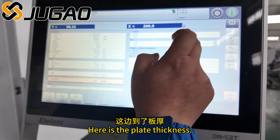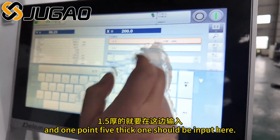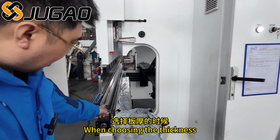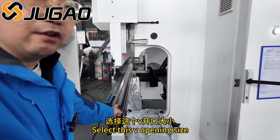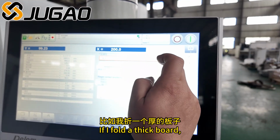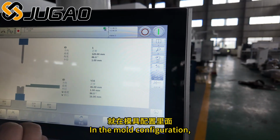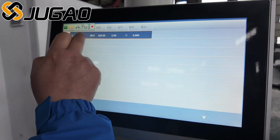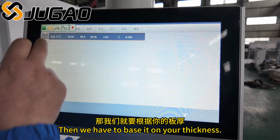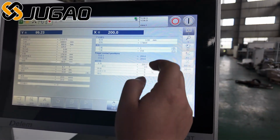Here is the plate thickness. For example, if I want to fold a 1.5 thick one, it should be input here. The plate thickness will be adjusted accordingly. When choosing the thickness, select this V opening size. Generally, it is 8 to 10 times the plate thickness. If I fold a thick board, when choosing the mold later, in the mold configuration, we need to select the upper mold. Then we have to base it on the plate thickness you use to choose the mold.